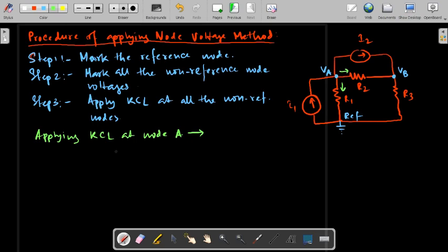Now I have told you earlier that for solving a particular circuit, the basic things needed are the element equation, KCL and KVL. Also for this node voltage method, we will apply KCL, KVL and element equations. We will go for applying KCL right now, and we have already applied KVL automatically while considering the node voltage that I showed in the last slide. So already KVL is applied.